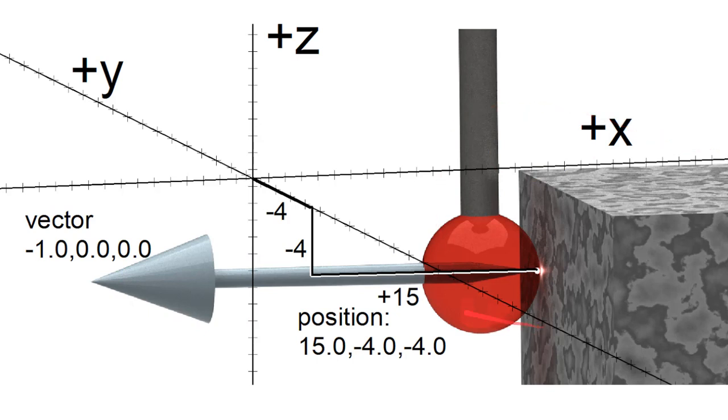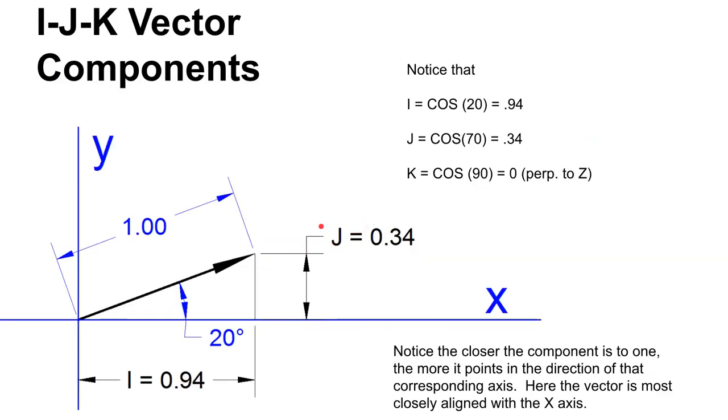And you might say, well, that seems unrealistic, because we just got through saying that this face on here is not going to be perfectly aligned with the x-axis. But keep in mind that the machine, even if we were jogging slightly in 2 axes at one time, when we probed this point, would snap this vector to the nearest axis of motion. And so it's pretty common to get vectors like this when you're probing manually. But I guess I'm getting a little bit ahead of myself. Let me back up here.